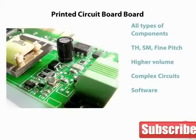There was a time the only way to make a prototype PCB for the experimenter was to take a board with a full copper plane on it and apply resist to the circuit traces. The whole board was then dipped in a very strong chemical that would etch the remaining copper away, leaving the required traces. Holes then would be drilled, and then finally you had a crude board. Commercial quality boards were out of reach for the average individual without incurring a very large first cost. Thankfully, we live in a more modern age, and it is fairly easy now to generate a high-quality circuit board using PCB software and the services of a board house for a very reasonable price.